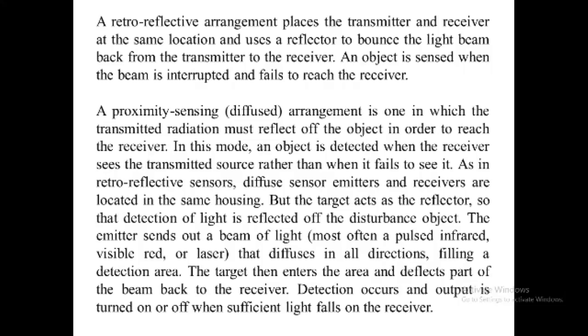Through beam sensors can be used to detect very small objects, to detect the fill level inside a container, to detect spliced or overlapped material, to detect the precise location of a specified object, to detect the content of a container, and to detect opaque objects. The advantages of a through beam sensor are that it is the most accurate type of sensor and it has the longest sensing range of the three.